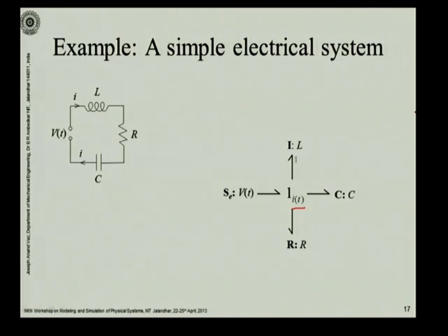Again, let us identify these bonds. We have got them 1, 2, 3 and 4. There are only 4 bonds needed. We can again draw the stroke for causality. We have the end which receives the effort. Again, because this end is a source of effort, naturally the stroke will have to be placed here. We will explain about causality of I and C elements later. So here we have again all the cause and effect represented on this system itself.